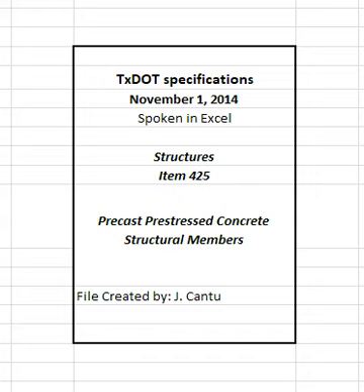5. Payment. The work performed and materials furnished in accordance with this item and measured as provided under Measurement will be paid for at the unit price bid for prestressed concrete of the specified structural component and type or size. This price is full compensation for fabricating, hauling, and erection of the members, furnishing and tensioning of prestressing steel, furnishing and placing reinforcing steel and duct, furnishing and placing bearing plates, elastomeric bearings, bars, anchorage plates, and appurtenances, grouting holes, repairs, special treatment of end anchorages and shoes as required, erection bracing, and equipment, labor, tools, and incidentals.